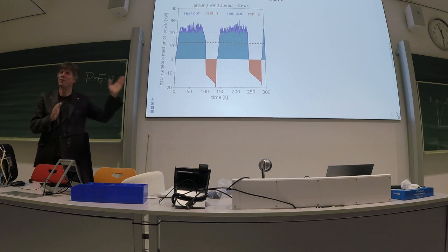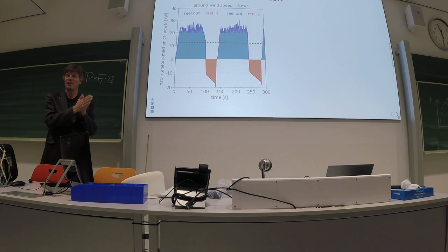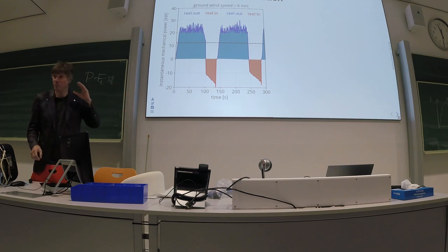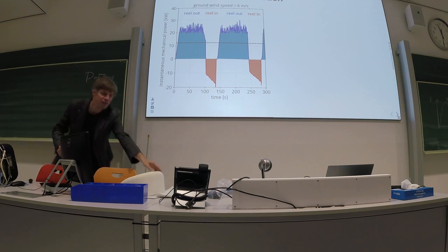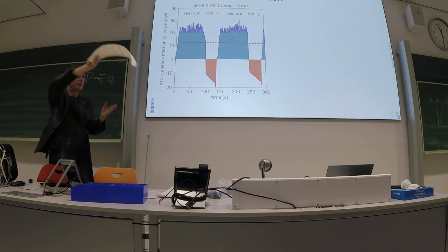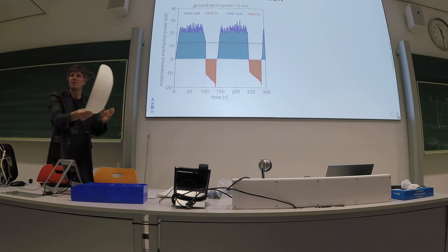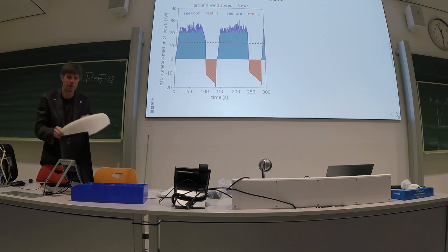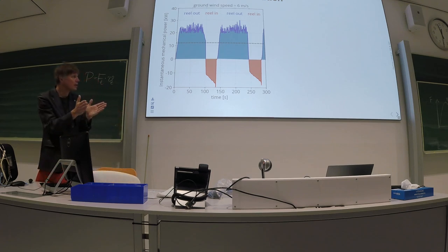So in the theory later, you will see that the closer the tether is aligned with the wind vector, the higher the force. This is a core principle of airborne wind. We'll show this mathematically in the next lecture. But just from that concept, you can imagine if the kite flies, the tether is sometimes more aligned and sometimes less aligned with the wind vector. And this change in alignment, as you mentioned, is the underlying core reason why we see these fluctuations.